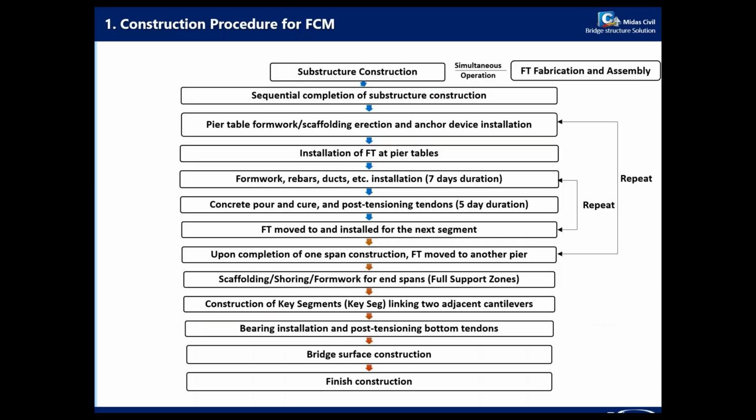When we begin the construction, we start with the substructure construction. After the substructure construction is finished, we can install the form traveler on the pier.